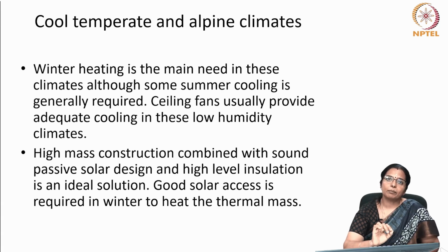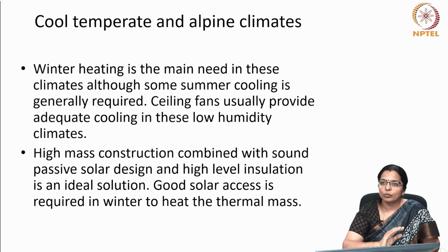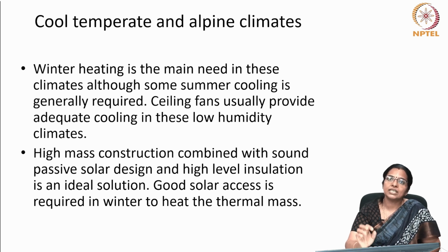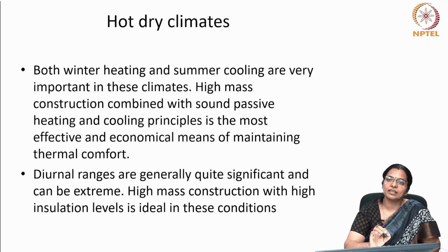In cool, temperate and alpine climates, winter heating is the main need in these climates, although some summer cooling is generally required. Ceiling fans usually provide adequate cooling in these low humidity climates. High mass construction combined with sound passive solar design and high level of insulation is an ideal solution. Good solar access is required in winter to heat the thermal mass.